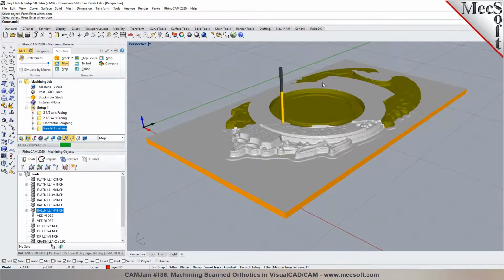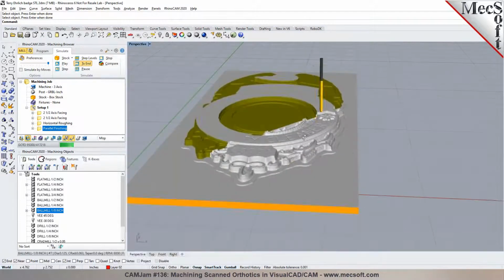And if you didn't want the cutter to go into this circular region in here, we could have eliminated that by selecting an inner region, so the cutter would stay between the two. It would know the topology of the geometry you selected, so it would stay between the two areas only. Okay. And anytime you want to skip, we can pause and select simulate to end. You'll notice that it's going to run through the simulation.